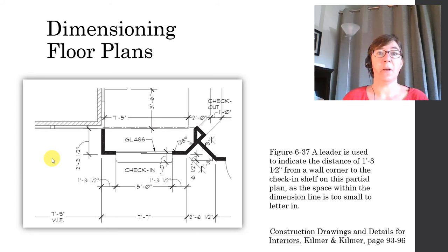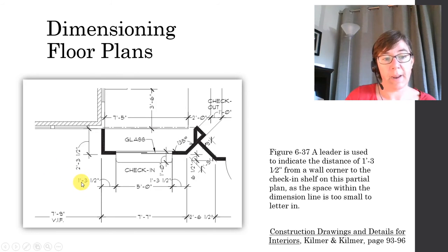Sometimes, for some of your smaller dimensions, the actual text that you want to include doesn't fit between the tick marks. It's too wide. In that case, we pop the text outside of the dimension, and it's very common to include a leader line. It could be an angled leader line, or in this example, they used a curved leader line. So let's take a look right here.